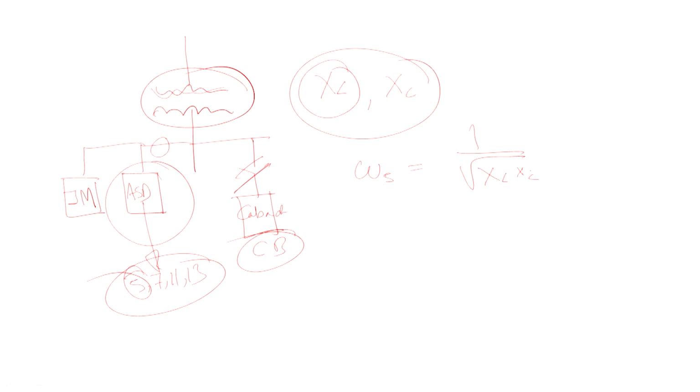It is basically L leakage and C. Ultimately, you have chosen a capacitor to mitigate this problem, but this entity is there. This entity will have a 5th harmonic and it will cause a 5th harmonic